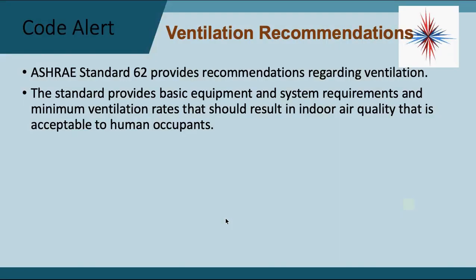So ASHRAE Standard 62 provides recommendations regarding ventilation. When you look in International Mechanical Code, they don't use the word recommendations. They use the word shall, S-H-A-L-L, which means you will. So there's a big difference. ASHRAE standards are recommendations, but all of the codes go back to ASHRAE standards. The standard provides basic equipment and system requirements and minimum ventilation rates that should result in indoor air quality that's acceptable to human occupants.